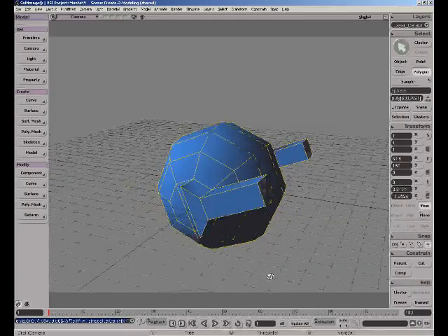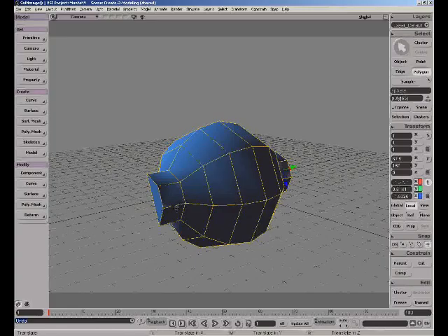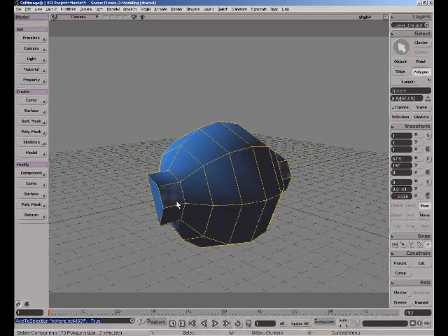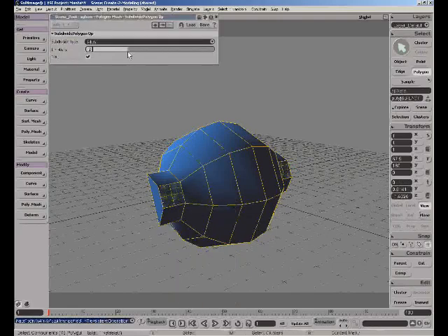We could do it like that, or we could also, if I undo this a couple levels, let's go ahead and use the new Subdivide tool. So if we click on here, select this polygon, right click, subdivide these polygons, and now we have a number of different patterns we can choose from to add definition to that selected polygon face. So here I have the diamond pattern, the X pattern, and you can see we also have a slider to control how many iterations we get of that particular pattern.